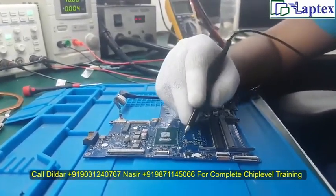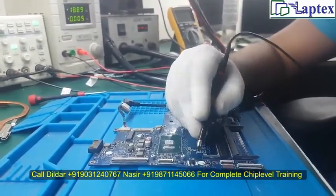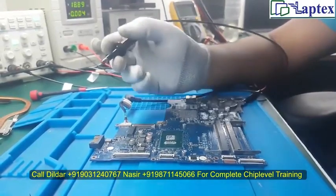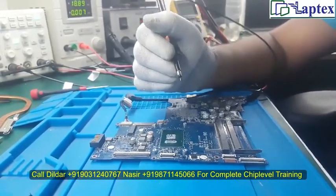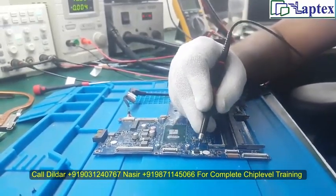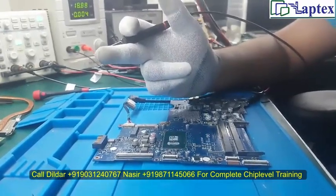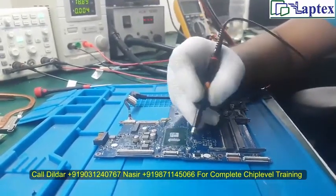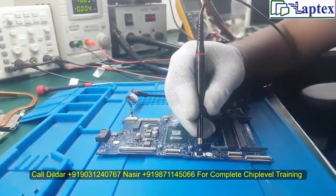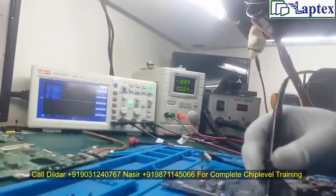When you select any BIOS program, it is written that it allows reading and writing at 48 megahertz, or there could be 17 megahertz. Each and every BIOS is different. Maybe you are using a BIOS instead of the customer's original BIOS, and it may not be selected because of a mismatch of the frequency. So what you have to check here, keeping your probe on pin number 6,